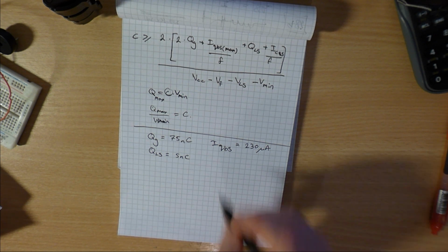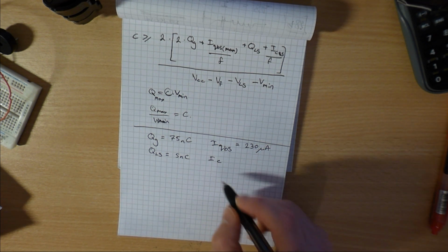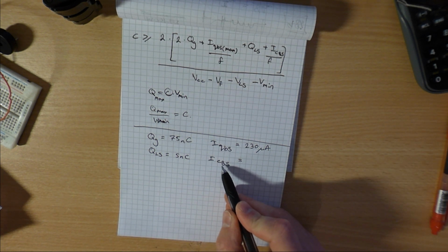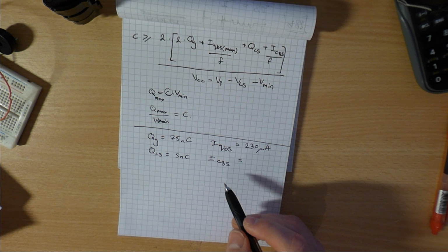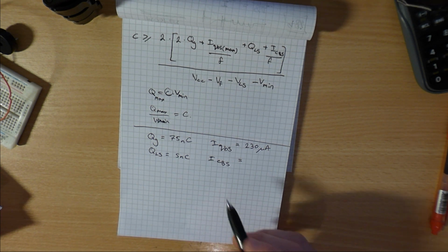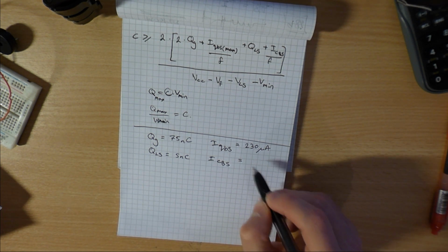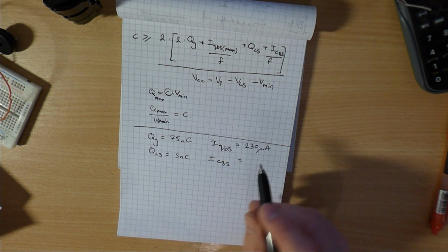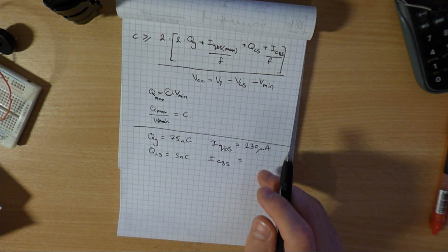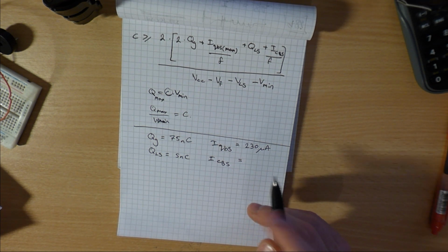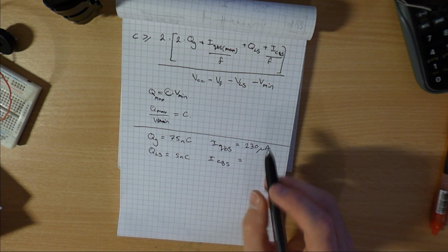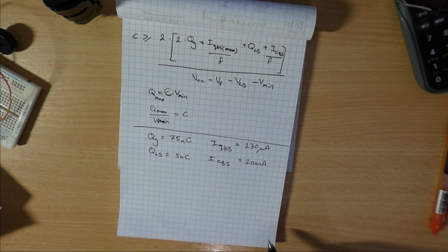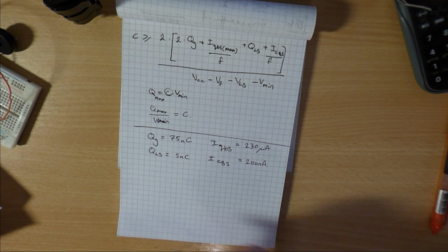volt gate driver. And then we've got ICBS, and this is the leakage current of your bootstrap capacitors. I don't have a data sheet for the capacitors that I've used because I've just got them out of my junk bin. If you're using only ceramic, which there's nothing wrong with, if you can make up enough capacitance with just ceramic capacitors, do so, it would be much better. But if you're using electrolytics at all, then they do have an amount of leakage. I'm going to say 200 nanoamps for mine, just as a generic value.